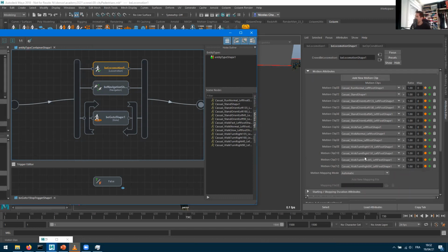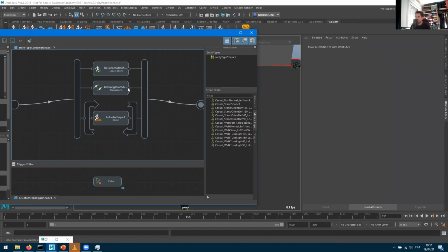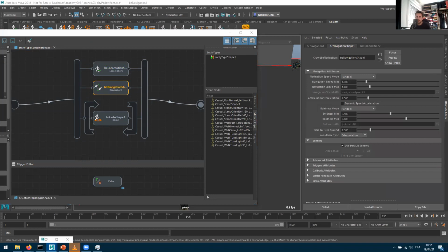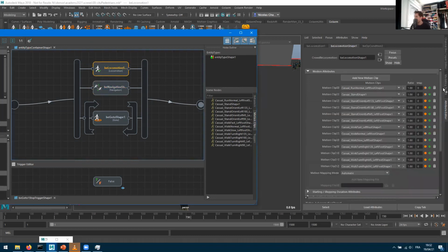So if you've got motion clips, shape, whatever, 1, 2, 3, 4, 5, just unselect and reselect, and you should get the UI proper. Whenever the UI is not refreshing, just unselect the node and reselect the node, and you'll get your UI refreshed. So, okay, let's go through that again. As I said, every single motion which is a turn can be mirrored. So please mirror those 8 animations. Make sure that you've got that orange full moon on those 8 motion clips.